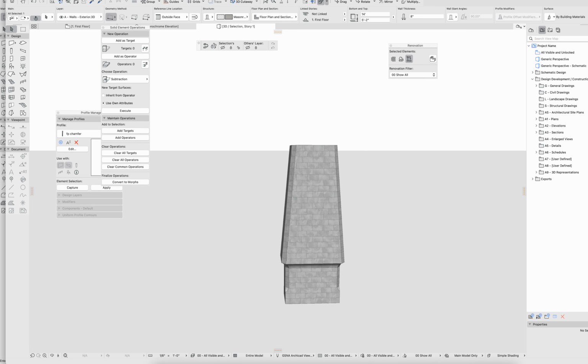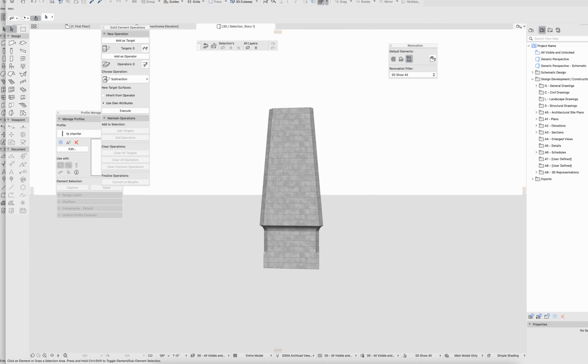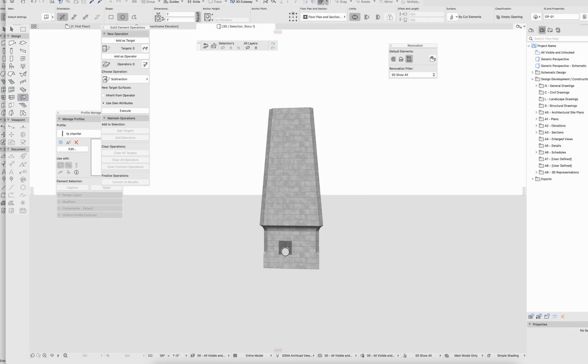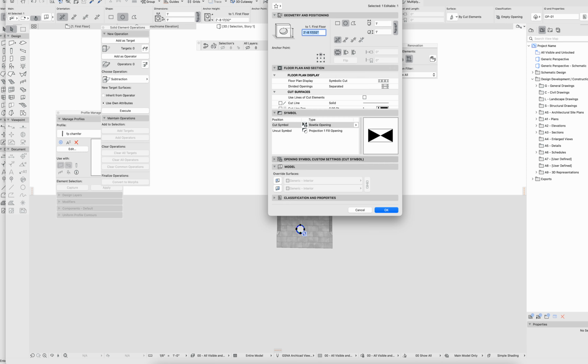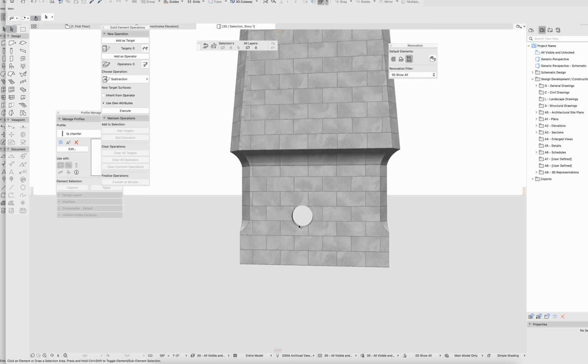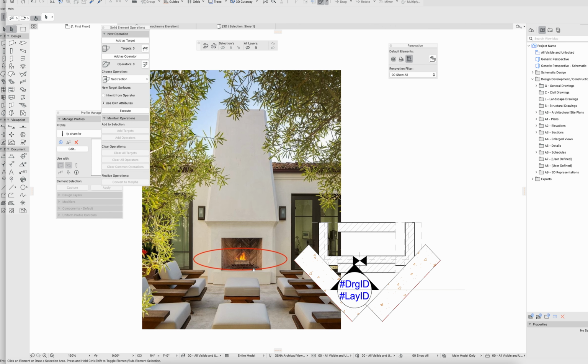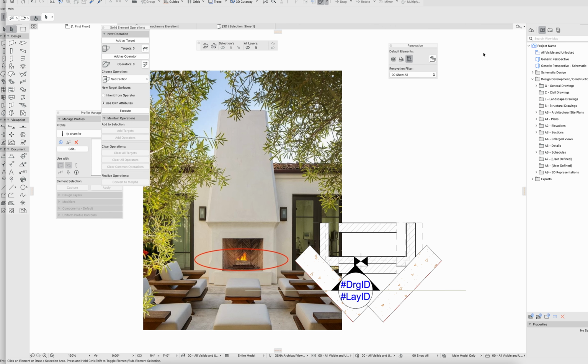And obviously, you can get the exact dimensions, the angles and everything. The other thing is, for the fireplace opening, you could use an actual opening here. So if we drop that opening, you can say if it's an arched or square opening, or a custom opening, and you could actually make that shape whatever you need it to be. For the inner pieces, I would add a slab for the hearth, walls for the brick liner, as detailed as we need to be at this early stage. So that's kind of a quick bumble through trying to make something similar to this.